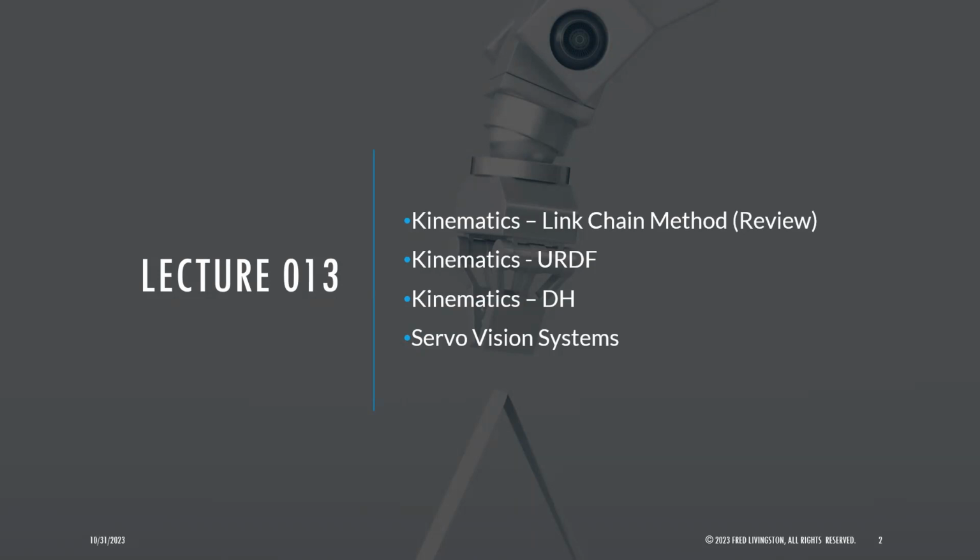And then I want to combine everything together, and that's servo vision. You detect an object, see its location and pose, and now you want to grab it. So I want to figure out what it is, make my end effector equal to the object's pose, and then back-compute the angles to make the robot move. I wanted to show you a 3D example of that, and I'll probably show it when we do the labs on Thursday. That's kind of wrapping up the material at that point.